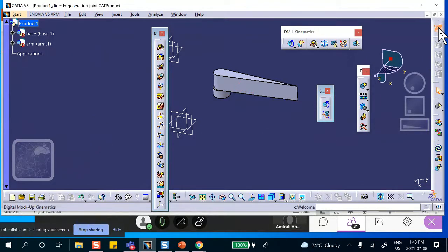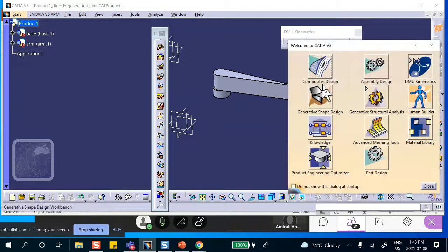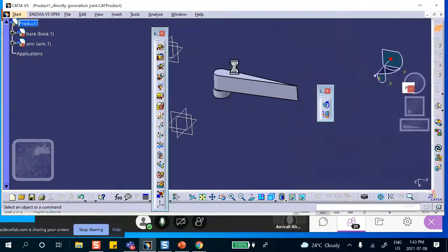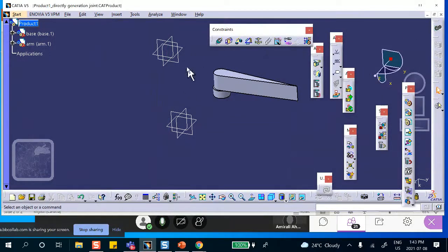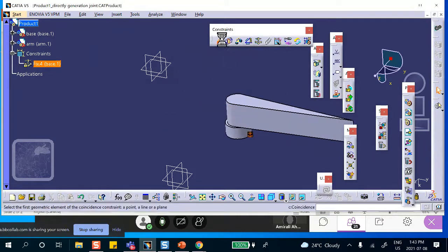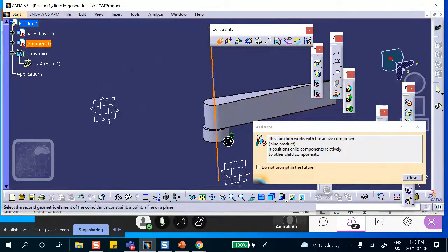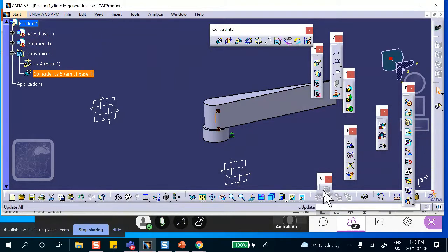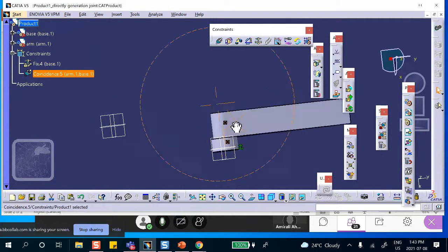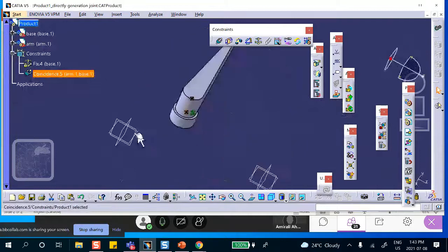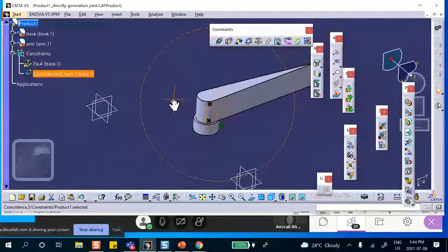Okay. So let's go to assembly design, because we agreed that some people may feel more comfortable. First of all, let's anchor the base there. And I'm going to create a constraint between this axis and that axis. There is nothing to update because it was already coincident. Notice that before, I did that plane to this plane. I am not going to do that plane to this plane.